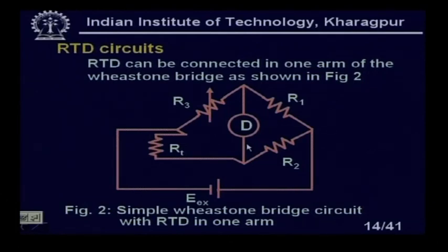That means a wire will be like this and there is a contact that will move like this, and this length will be calibrated in terms of temperature, like a conventional, school-level potentiometer, where I will have a graduated scale. So, if I move this, I can balance the bridge, and this will be calibrated in terms of temperature, by which I can measure any unknown temperature, right.